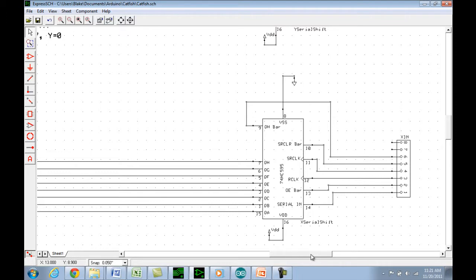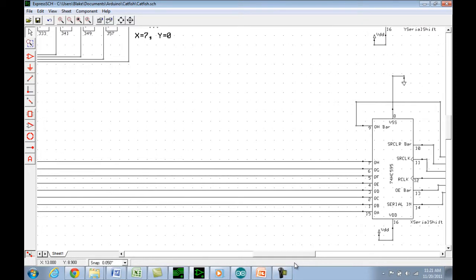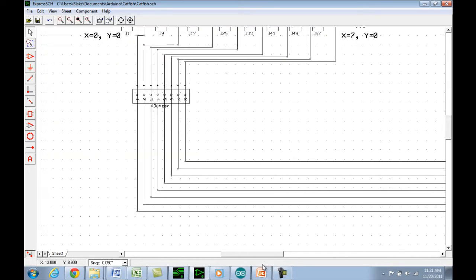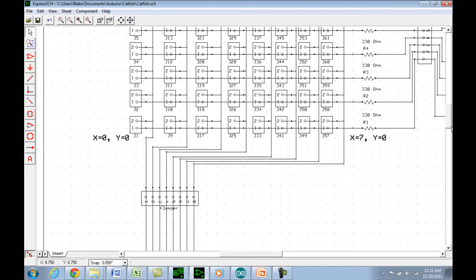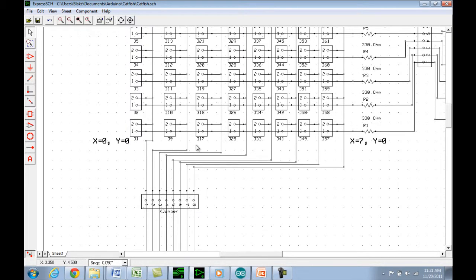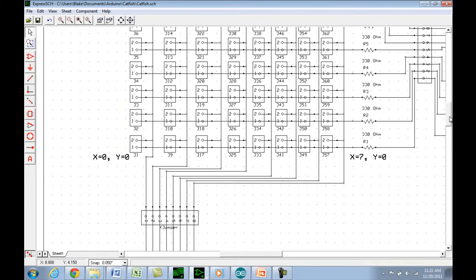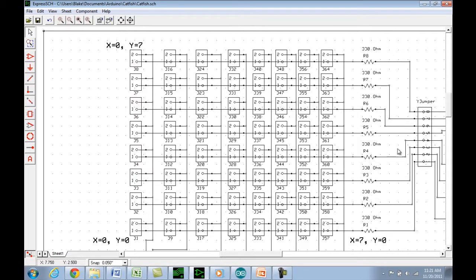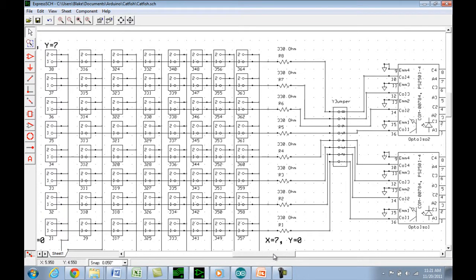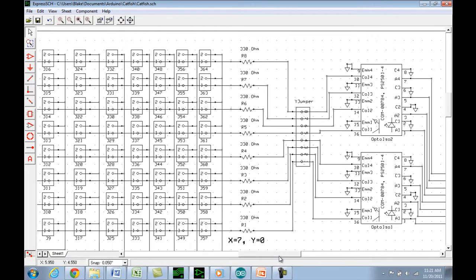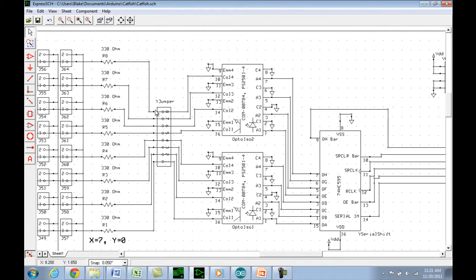Well, for the X direction, the data word comes in and it spills out onto the lines. There's 8 lines, because it's 8-bit, and I zero index, so it's from 0 to 7. And then here's the LED array, so there's nothing limiting that side. For the Y direction, you come out through some current limiting resistors here, 330 ohm,